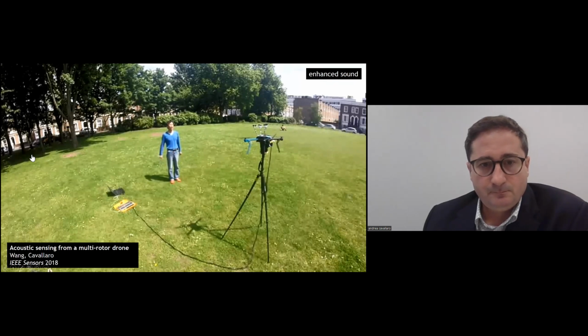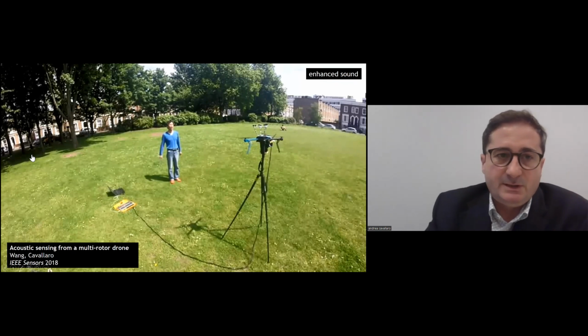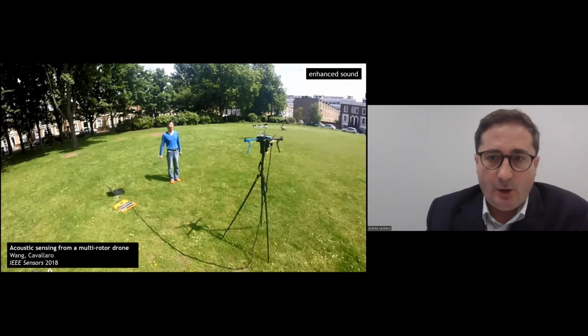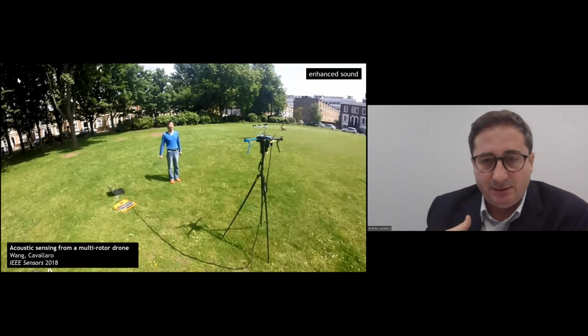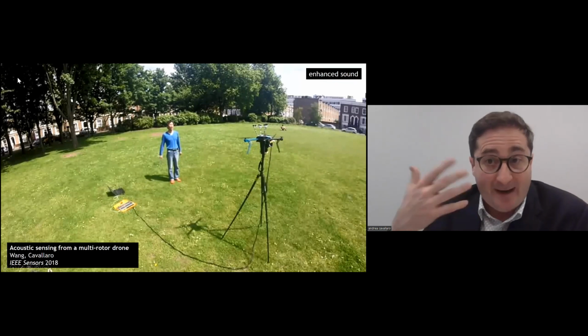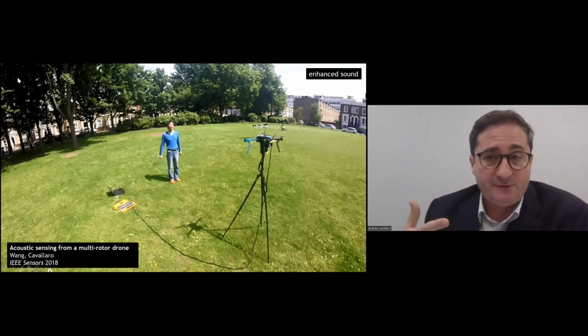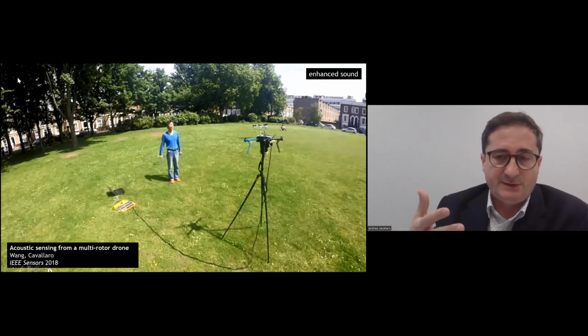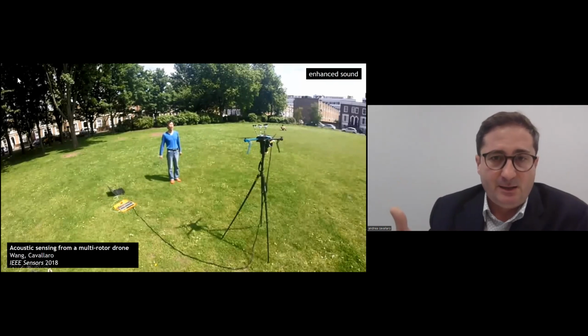17, 18, 19. So here is the ability of the system to determine how to extract the relevant signal, assuming that we have a number of microphones that exceeds the number of sound sources. In this case, the sound sources are 5: the speaker and the 4 propellers.